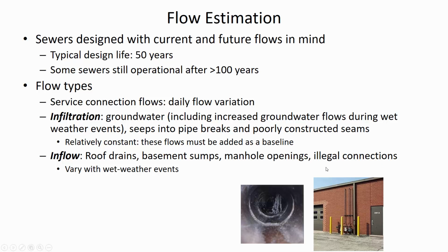The roof isn't polluted. But if this is being discharged to the sanitary sewer, which is going through a really lengthy process of biological treatment, then that can add a lot of additional cost to the treatment, just the additional volume. Even though it's diluting the waste constituents a little bit, still the majority of the cost is related to moving the water from place to place and aerating the water and not so much related to the concentration of the pollutants in sewage. So both of these are bad things. It's just better if people allow rainwater to discharge over their yard to try and get the water to seep down into the soil with grass.